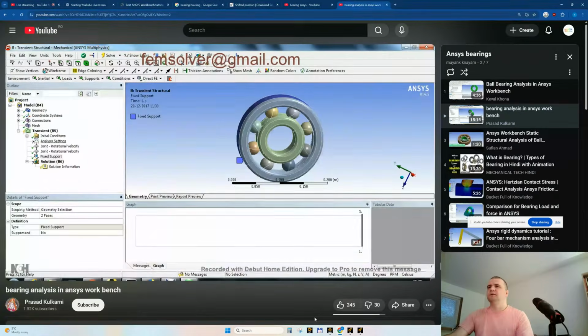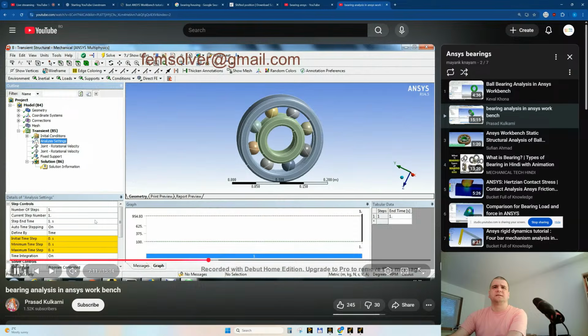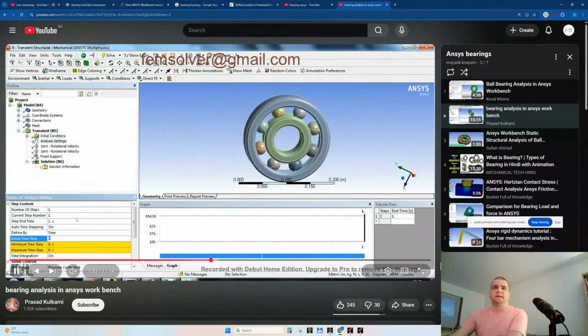Back to our video. Fix support, analysis settings. This should be nice. He does it in one step, initial time step 0.1, 0.01, 0.1. I don't know, because he has almost 1,000 rotations per minute and he's using such a big time step. I have my doubts here. Direct, I like iterative instead of direct. Oh, okay.